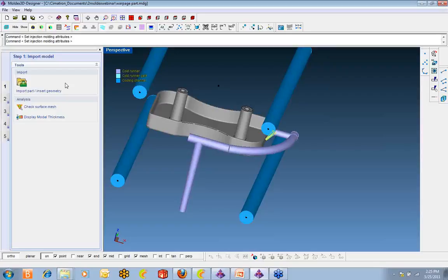You're going to need the attribute for the cavity as well. Okay, now we're going to generate the mesh. And you can see that I have an accuracy level of 1 to 5, 1 being the fastest, 5 being the most accurate. And I'm just going to hit OK here. And then choose Generate.